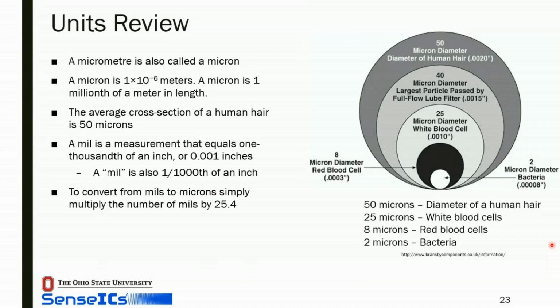It is not a millimeter. A millimeter is a completely different thing. That's just something I think is useful to know. If you're going to a place in Europe or Asia, then you need to know about microns. One micron is a tiny thing. It's 10 to the minus 6 meters. Human hair is 50 microns. So 1 mil is actually 25.4 microns, FYI. Those are things you need to have in your mind when you're talking PCBs or working with vendors, and also when you're doing the design activity itself.